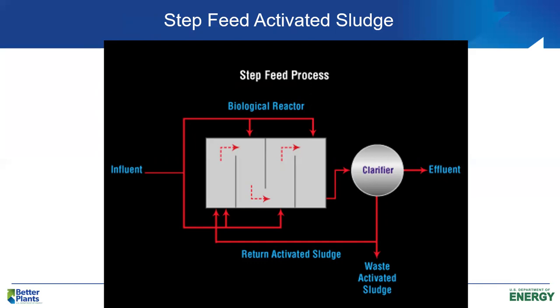So what we're doing, we're again adding the organic loading along the length of the reactor. And this again helps even out the organic loading, helps us almost approximate the complete mix activated sludge process. But again, it's a very flexible type of reactor and process, so we have an opportunity to actually operate in different modes, by the way, when we manipulate the influent loading.